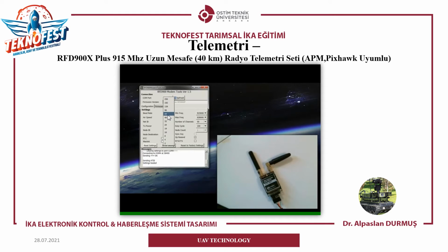Right now the pictures are being sent in 10,000 bit packets. If you get any error in there, it'll resend that packet. If you increase the airspeed, this is the data rate the two radios are talking to each other, you can get more bit errors, which will result in more packets needing to be resent, which can make downloading the picture take longer. What we found is 48 for the airspeed to be the sweet spot of not taking forever to download a picture, but also not incurring a bunch of bit errors to where we have to resend a bunch of packets.